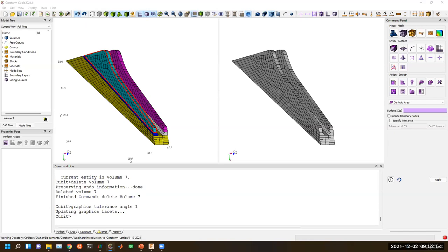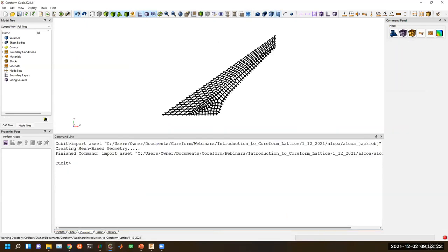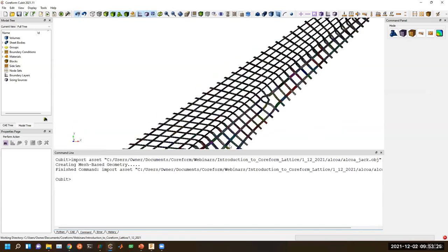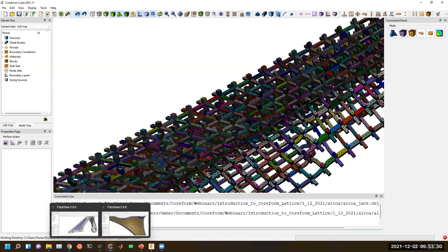Ada has a question about the deformation of a geometry and mesh. If he has built and meshed a lattice cell, for example a cubic shape or an octet, and now wants to stretch it in a specific direction, he might think of doing it by multiplying the coordinates with a transformation matrix. He wants to know if this is possible to do in Cubit. Yeah, this is actually something that I did. I made some test samples back in the day. By the way, Ron, we've now imported the mesh back, so we could build our tet mesh from this if we wanted. And again, that could be in Cubit.